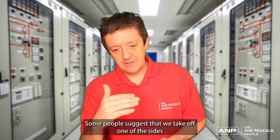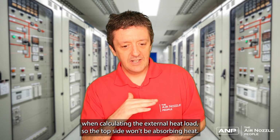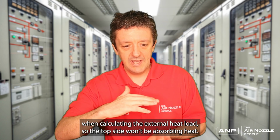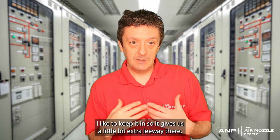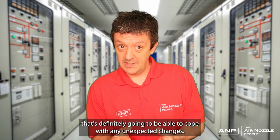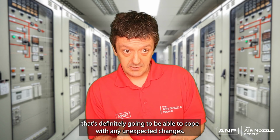Some people suggest that we take off one of the sides when calculating the external heat load, so the top side won't be absorbing heat. I like to keep it in, so it gives us a little bit extra leeway there, so we're getting a truly robust solution that's definitely going to be able to cope with any unexpected changes.